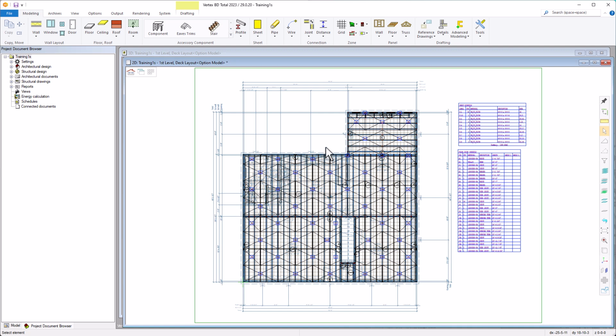Now in this case we have both our floor framing and our sheathing. If we wanted to make a drawing for each one of these, when we get to the point of actually creating a PDF or a drawing, we could assign a layering style or a layer group. We can use this to create two separate drawings, basically by controlling the layer group. Just to give you an example, go over to the floating toolbar. Mine's on the right side, yours may be on top.